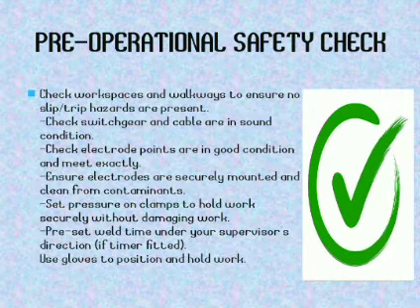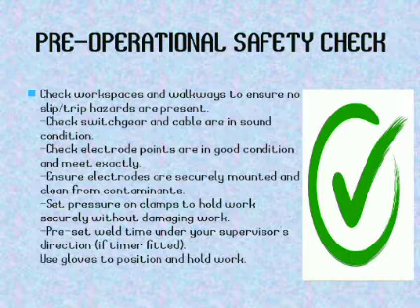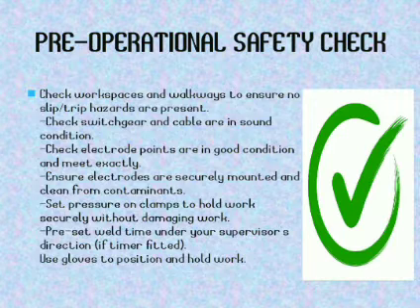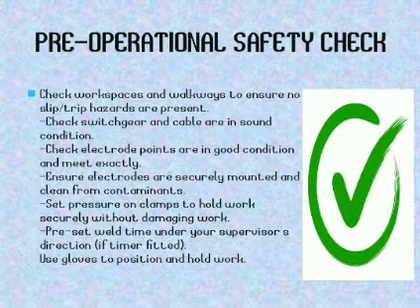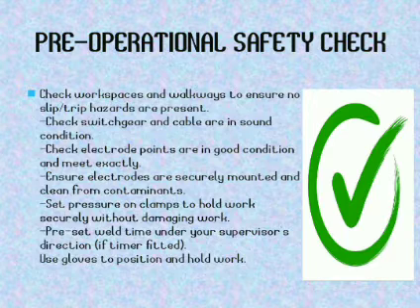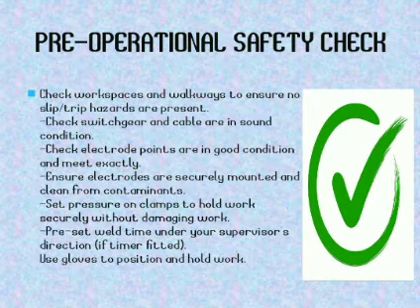Ensure electrodes are securely mounted and clean from contaminants. Also set pressure and clamps to hold work securely without damaging it. And preset weld time under your supervisor's direction if a timer is fitted, and also use gloves to position and hold work.